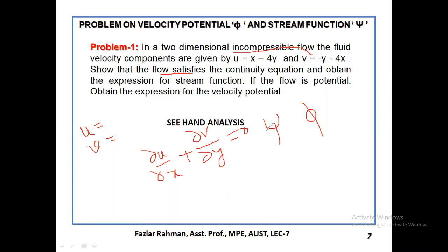Now, how will we figure out the function psi and function phi? You can figure out, for example, the relationship between this phi and u. You say the negative derivative along the x-axis of phi, I'm putting a negative sign, equals what? It gives you velocity in the same direction. That means this is u. Similarly, if you take del phi by del y, it will represent v.